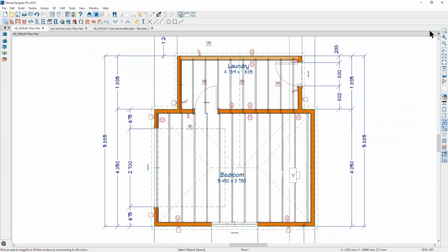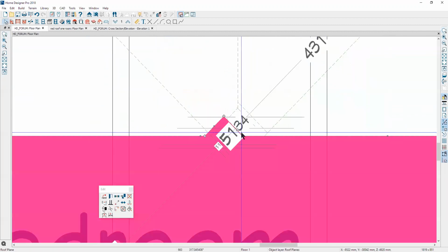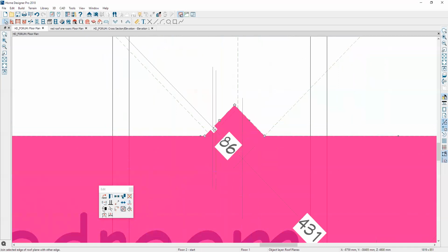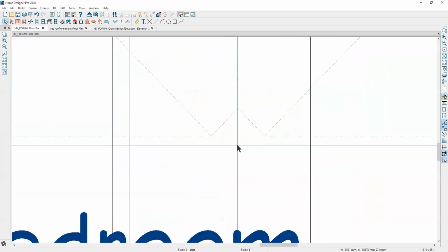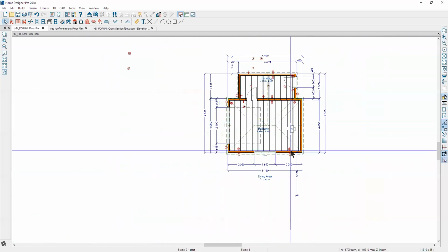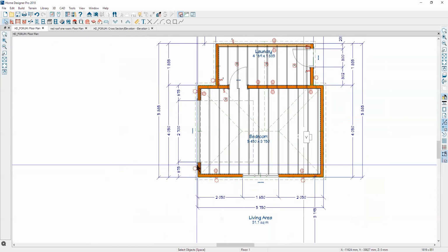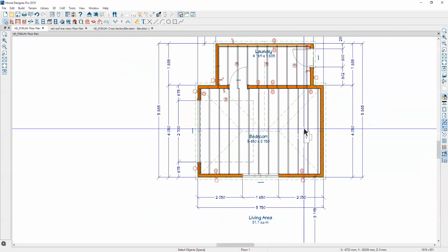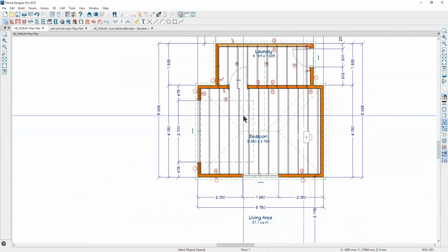I think I've answered. Well, I see a little detail here. See, these lines aren't connected properly. That should be connected there, and this one here should be connected to this little line here. Okay, that looks better. I'm not going to send these plans back to you. You should do this work yourself, based on what I've shown you is causing your problems. And you can undo that, and then you should be able to build either manually or automatically your ceiling joists.